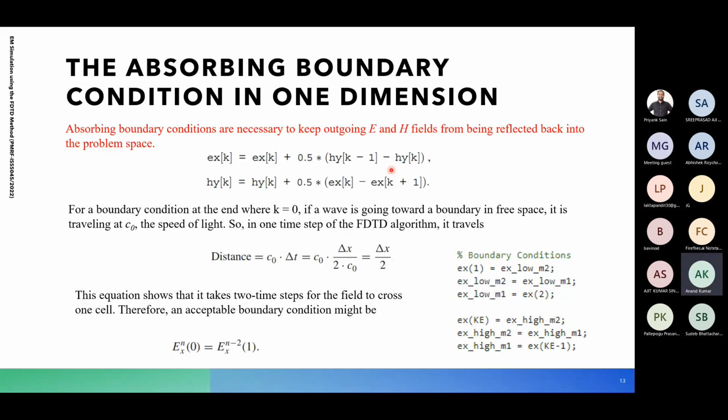So before excitation, no field exists. So we take it as zero, and when an excitation travels, we update the E field according to the excitation, the pulse, and then the H field is excited. So to satisfy the causality, we assume that no field exists over there. But in the equation, for every value of K, it is depending on the value of K plus 1, so the future value of K it will depend on.